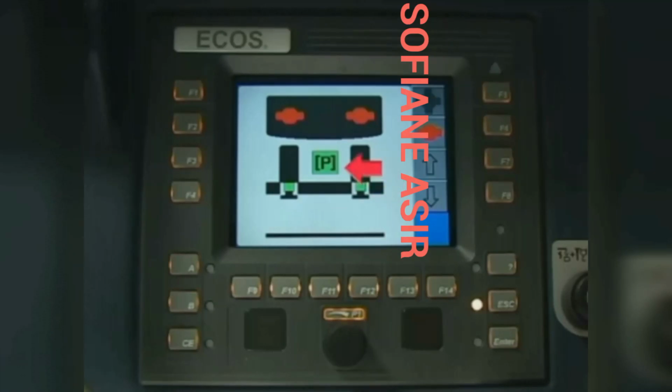The P symbol represents the pre-charge pressure necessary to hold the counterweight in the fully raised position. Green is with sufficient pre-charge pressure. Red is without sufficient pre-charge pressure. The LED on button A and the warning triangle will flash when the cylinders are locked until the required pre-charge pressure is reached. We will now install and then remove the counterweight.